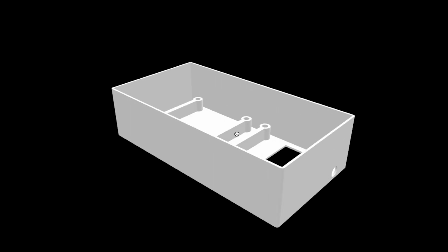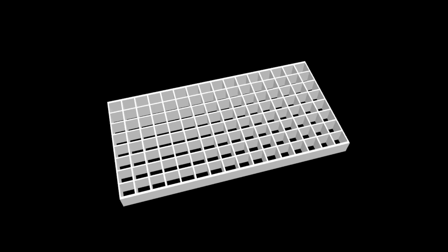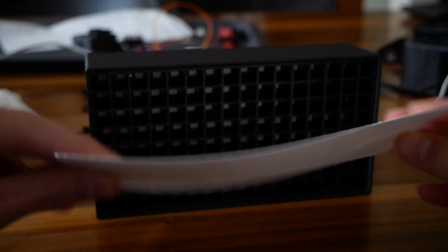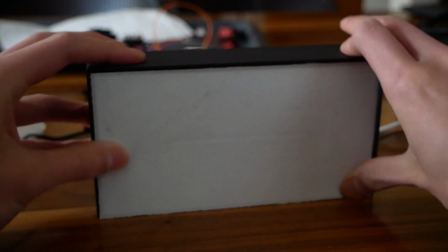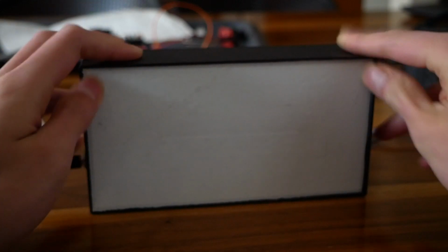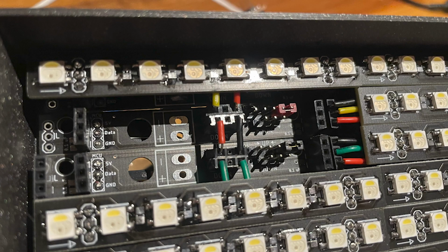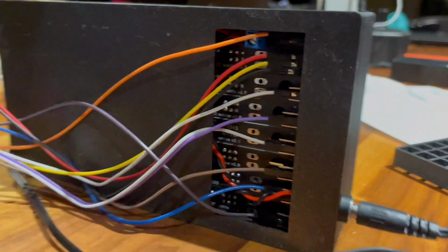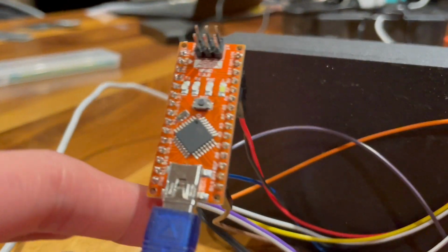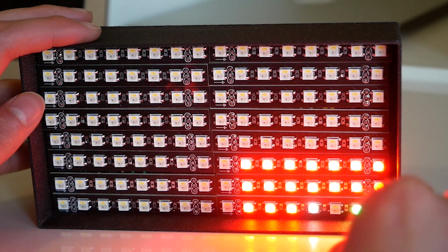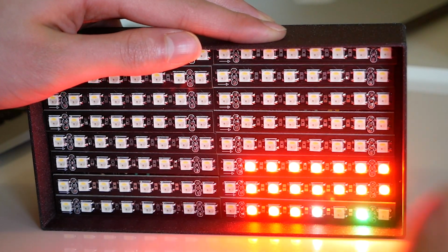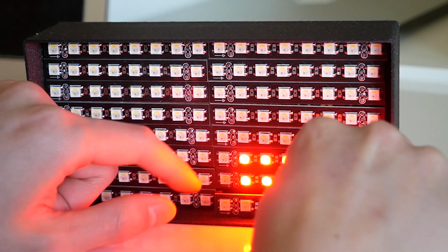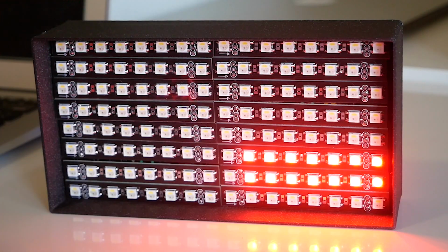In between coating and gluing, I also made a new larger case for the mini matrix with a thicker diffuser, serving as a nice complement to the large ping pong LED matrix. Like the larger version, these strips can be customized to any size and the data flow can be routed with jumpers. I've currently got them configured in parallel mode, where each row is controlled by port B and the two highest port A pins. In case of any failures, the NeoPixel strips are hot swappable with the base, where it can be popped off and put back without much work.